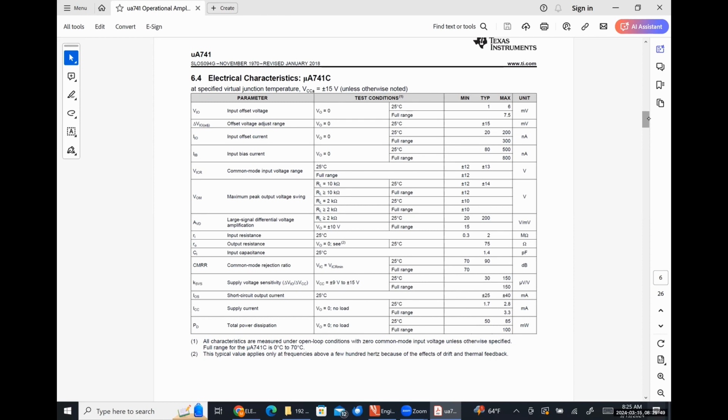That's what we should see for practically all operational amplifier circuits. Some special purpose op amp circuits, like those used in the processing of video, typically have a voltage gain that's only a few thousand, so not hundreds of thousands, potentially millions for other designs. But even though that open loop voltage gain is significantly smaller, we're going to find out that they all work roughly the exact same way.